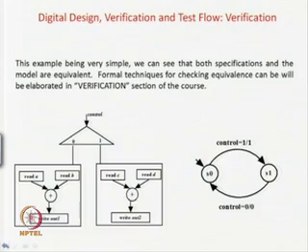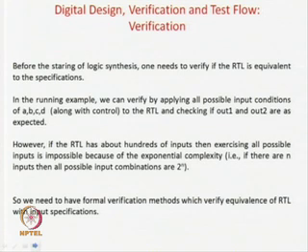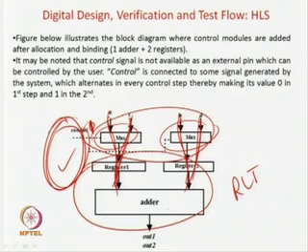Okay. And so, this is about the RTL design. So, we have gone to the logic design, that is actually called logic synthesis, but again this should be an equivalence preserving step. So, what do you mean by equivalence preserving? We had some adder description. So, here some adder description was there. It says it will do A plus B equal to C, this sum and carry, and it will also do C plus D. So, that is the basic job of the adder.